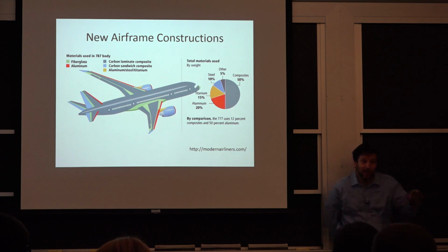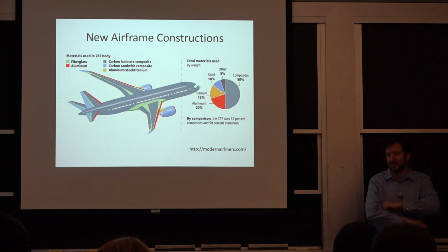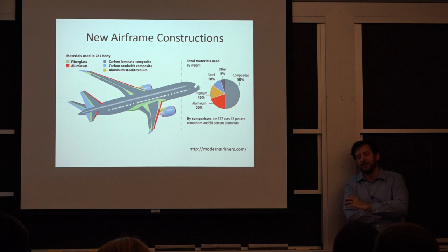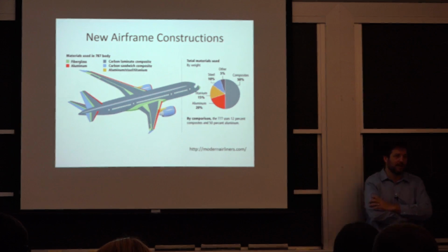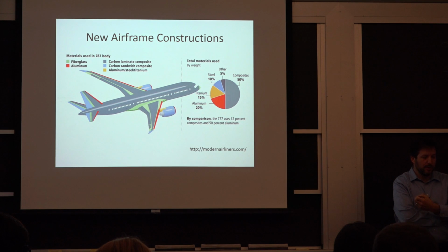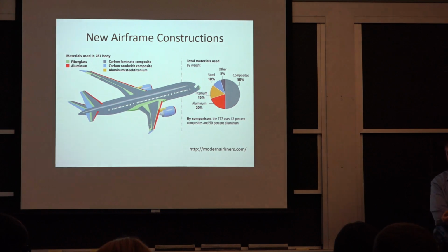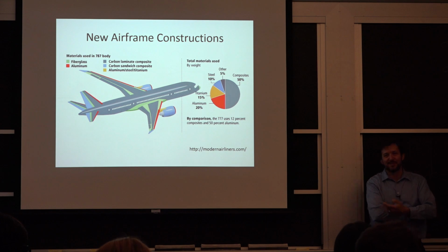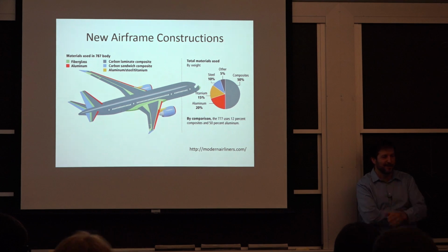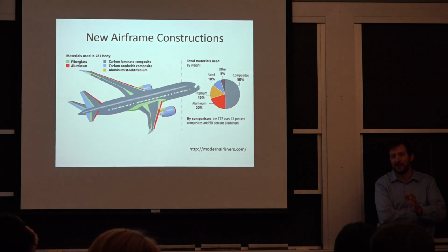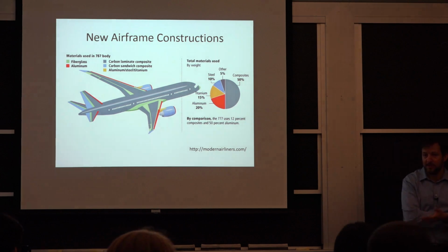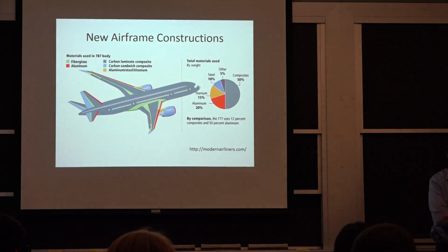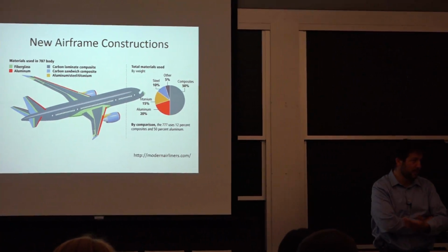And they started putting one panel and then maybe two, and for flight tests, but not for selling commercial aircraft. And part of the reason is, when we're talking about material and process specification, if you want to be super safe, you just get a copy of their spec and you get your stuff built with all these requirements of qualification of the people, the processes, the documentation. It's unbelievable. There's a reason, because we want this to be very reliable, and we don't want to just trust that people are gonna do what they say they're gonna do.